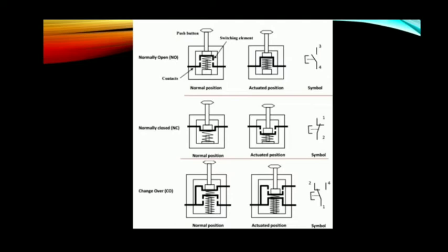They are primarily used for starting and stopping of operation of machinery. They also provide manual override when an emergency arises. Push-button switches are actuated by pushing the actuator into the housing. This causes a set of contacts to open or close. Push buttons are of 2 types.